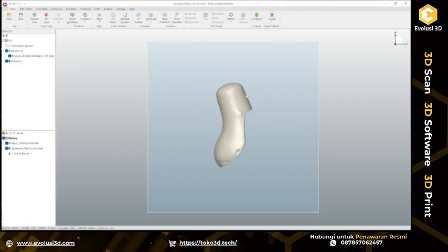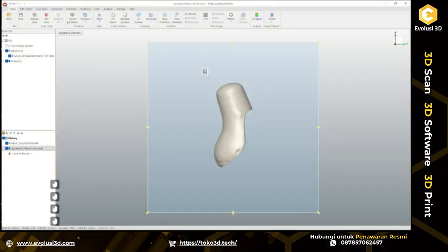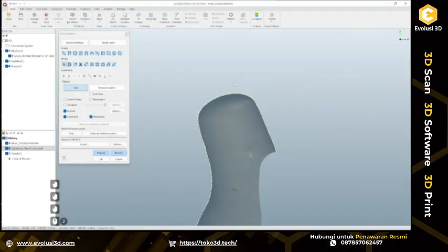What I would like to do right now, well, probably I can try to align it one more time by reorienting this lower part to be more or less vertical. Of course, I can always do this in an interactive way by rotating it and saying, okay, this looks good enough for me. Or I can go a different way: create a cross-section sketch, fit one straight line on this side, another straight line on this side, select both of them and create a middle line.